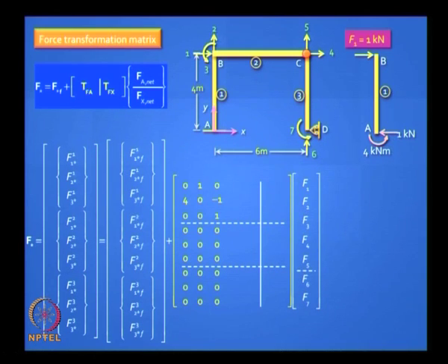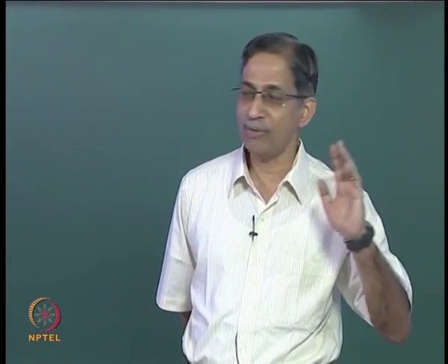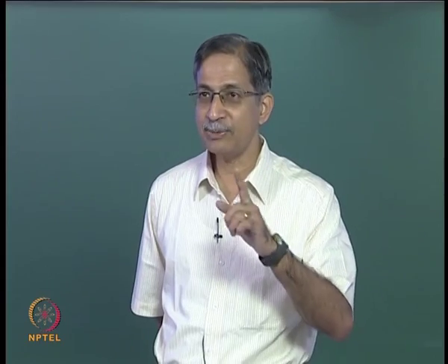I have written down the first 3 columns corresponding to F1 equal to 1, and I will show you F2 and F3 shortly. If you look at that first column, 0 4 0, is it right? Because only the first element will have non-zero items, second element will not be affected, third element will not be affected because this is a cantilever action for element 1, agreed? So that is why you got zeros here.